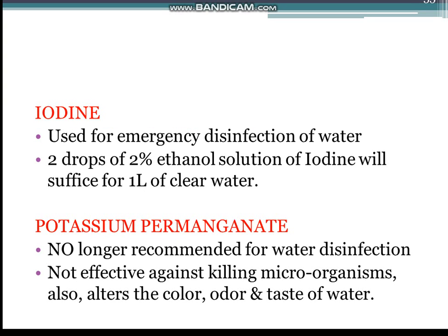Iodine. Iodine may be used for emergency disinfection of water. Two drops of 2% ethanol solution of iodine will suffice for 1 liter of clear water. A contact time of 20 to 30 minutes is needed for effective disinfection. Iodine is unlikely to become a municipal water supply disinfectant in a broad sense. High costs and the fact that the element is physiologically active are its major disadvantages.